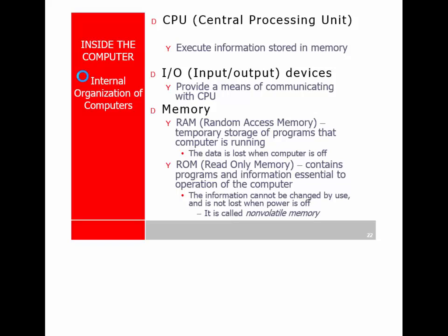When we look at how memory is configured, ROM and RAM are configured to the microprocessor exactly the same way. The only difference is in normal operation, we can't write the ROM. So ROM is a correct term. Random access is not a correct term. They're both random access. But this is memory that we can read to and write to, so read-write memory is a much better term for that.